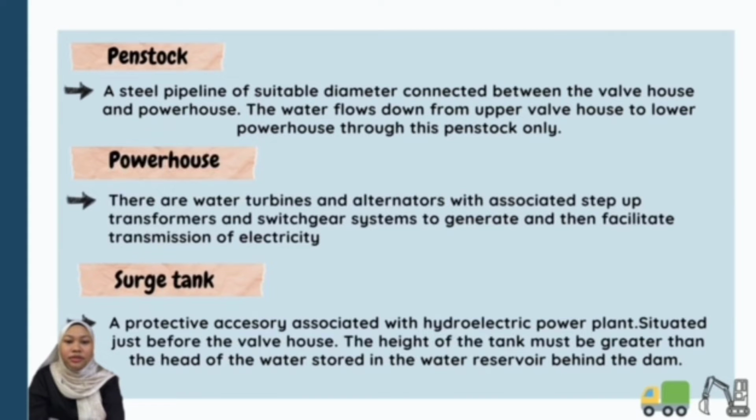The surge tank is also a protective accessory associated with a hydroelectric power plant. It is situated just before the valve house. The height of the tank must be greater than the head of water stored in the water reservoir behind the dam.